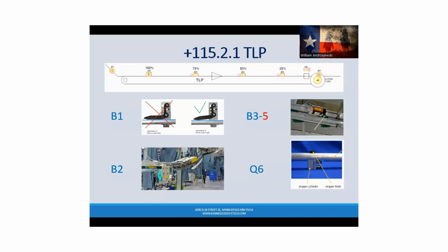And then if we need another one, then we start the numbering off at 31 through 38. And then you've got Q0, you've got a 0.1, a 0.2, a 0.3, a 0.4, a 0.5 for the additional modules if you did have a ton of sensors on that conveyor. You're never going to have a 9. Never have a 9. Never have a 0.